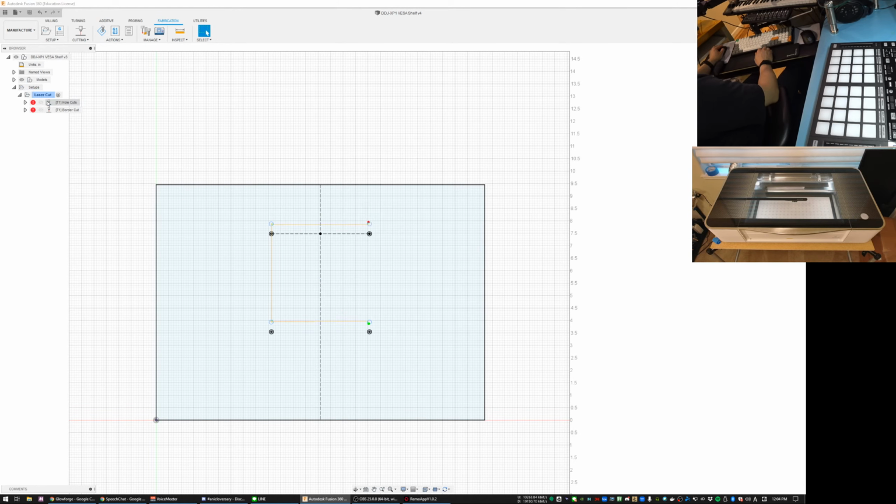The first operation is the hole cuts, and the way I specify this is you go to the geometry, right? And I can redo this. I'm going to say, okay, for this particular operation, which features within the sketch do I want this operation to represent? I'm going to select the 1, 2, 3, 4 holes. If I wanted to cut on this, I could select it, right? You can see where it's going to go, but obviously I don't want to cut on that construction line. So I've got 4